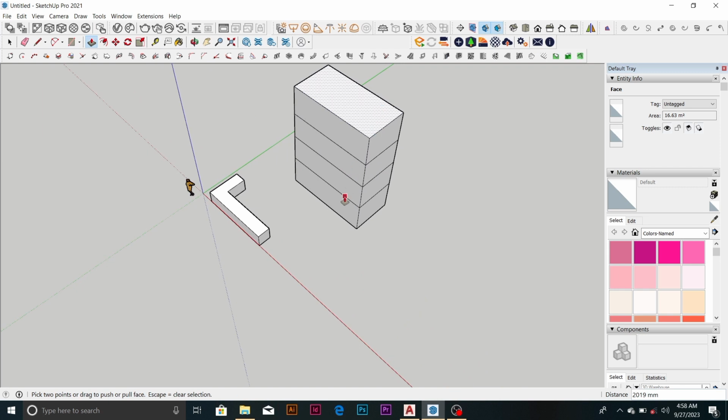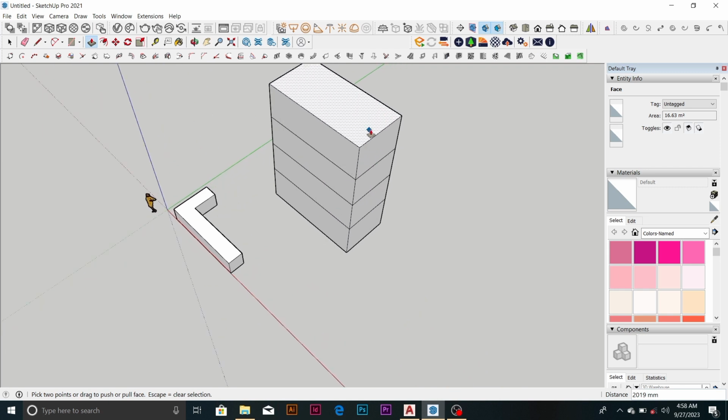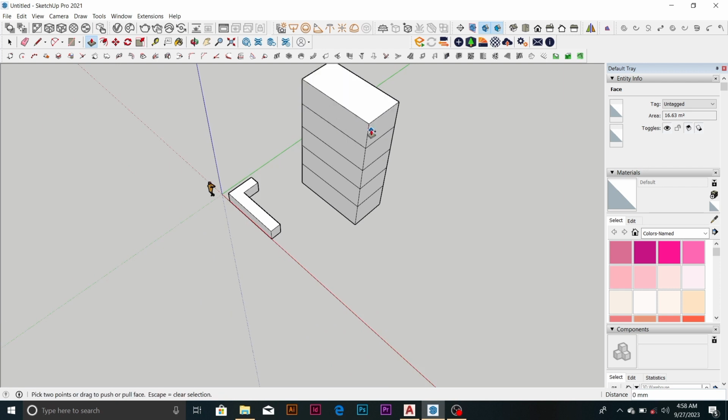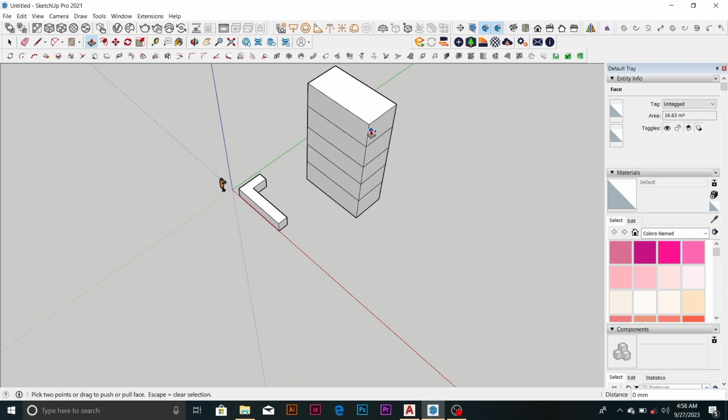Maybe you want to use the same height for the next one, maybe the last one. To use the same height, just press your control, double click it. It will continue. It's going to go to the height. So that is control used with push pull. The next one is practical. The third thing to learn is practical examples and scenarios where this shortcut shines.